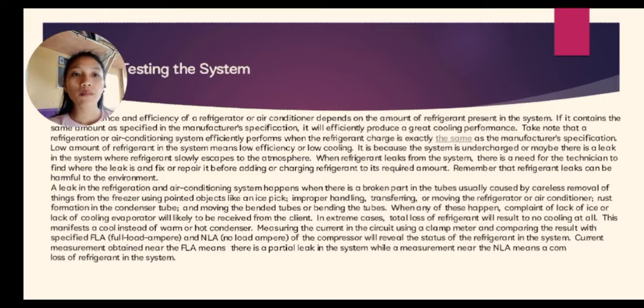Measure the current in the circuit using a clamp meter and compare the result with the specified FLA, full load ampere, and NLA, no load ampere.